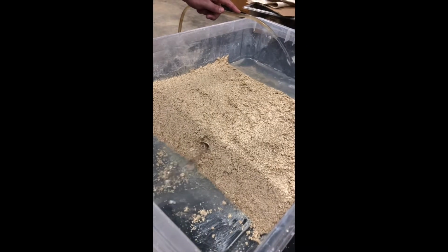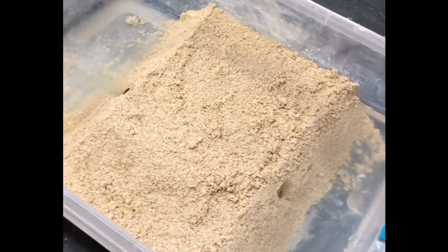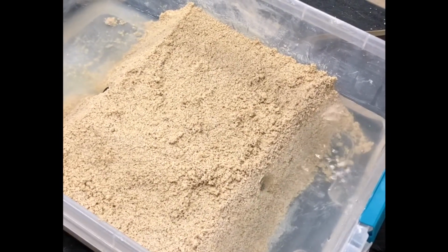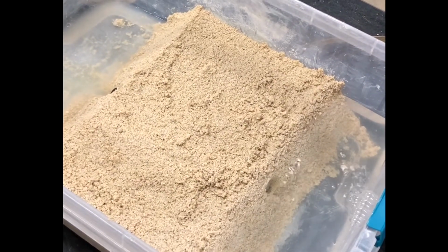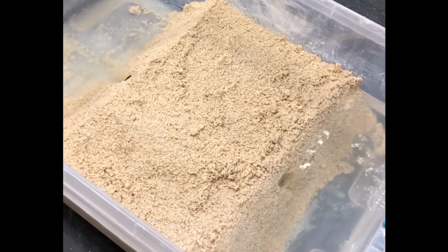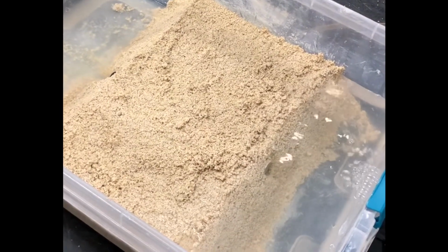Under normal conditions, the culvert is able to handle the flow and is not experiencing any failure mechanisms. In this demonstration, we are simulating an overtopping failure mechanic by totally blocking the culvert and eliminating outflow, causing water to pond on the upstream end and overtop the embankment structure, causing erosion across the entire system.